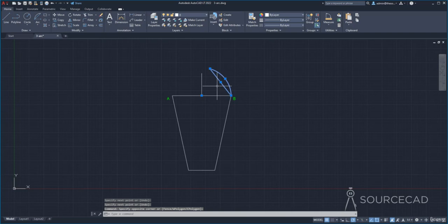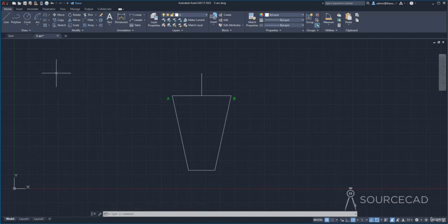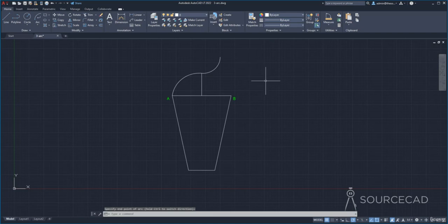All right, finally, let's talk about this last arc, which is continue. But before we do that, I'll make a simple arc, and actually I'll do that using 3 point. So I'll click on first point and second point somewhere randomly here, and then third point right here. Okay, now I'll go to continue, and this will happen. It will start making arc which is exactly tangent to the previous one. Now you can click on second point if you want to, or you can just move it in some other direction. Here maybe let's just make something completely different. I'll click here, and there we are.